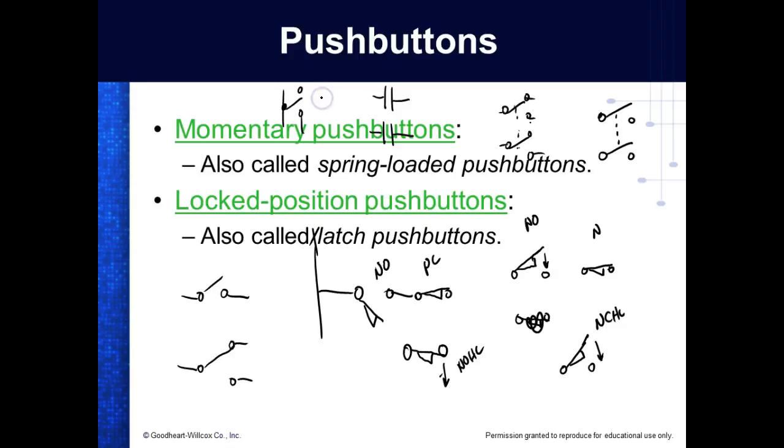And we've got these push buttons right here. We got a couple of double pole, double throw. Now, a double pole, double throw is going to require one normally open and one normally closed. So these push button stations are here. Here's the diagram. So this is the double pole, single throw. This is double pole, single throw. And this is the single pole, single throw, normally closed. Double pole, double throw, you can't say normally closed and normally open because when one of them's closed, the other one's going to be open. If you switch the position of the poles, then the contact depends on how you wire it.